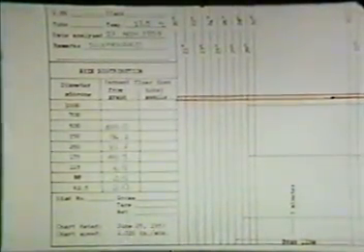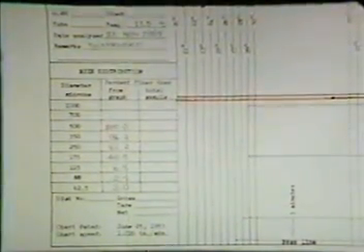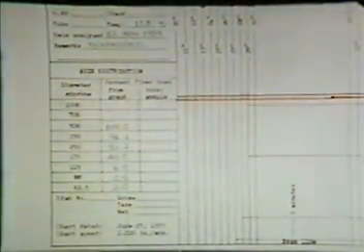From this chart, the percent finer than any given size in a sample and its gradation can be determined. It takes many analyses of many samples to obtain a realistic indication of the size composition of the alluvial bed.